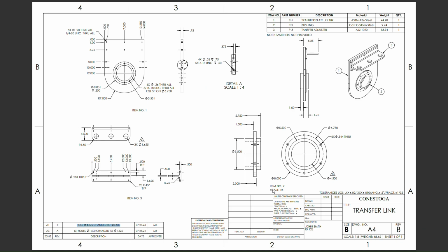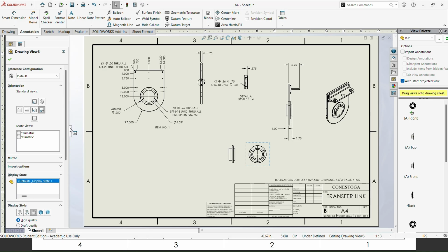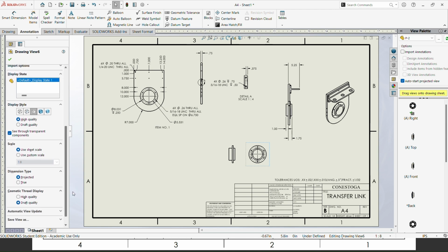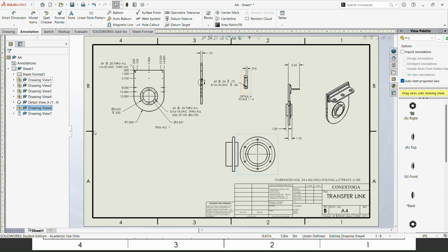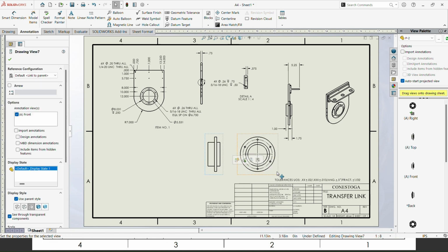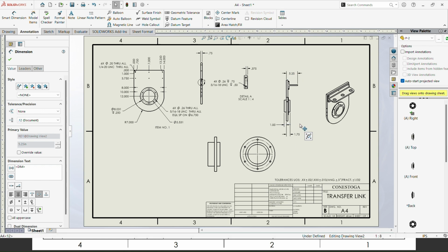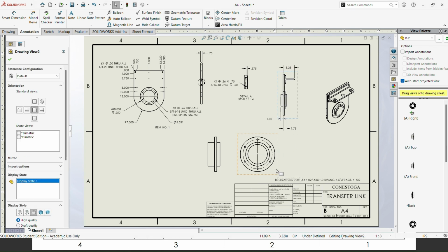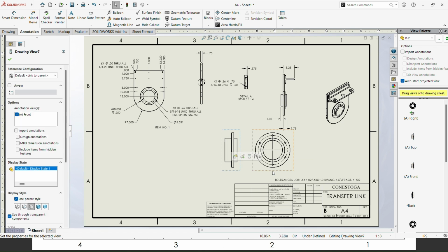You can see the scale here is 1:8, and I am going down to select the scale. I am changing that to 1:4. You can see it's bigger now. Just click OK. You can move this here. Okay, just make this little down and move this little up because we don't have enough space to put all this together. So we need to make it little tight.